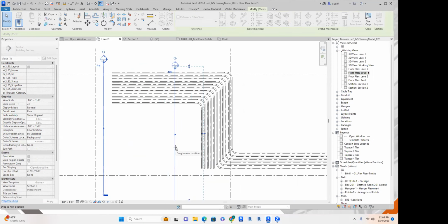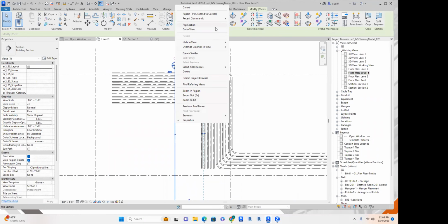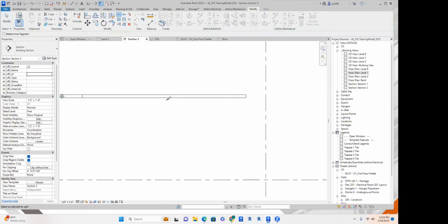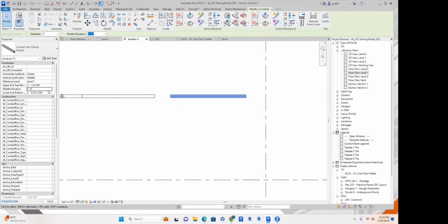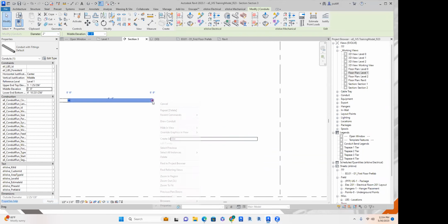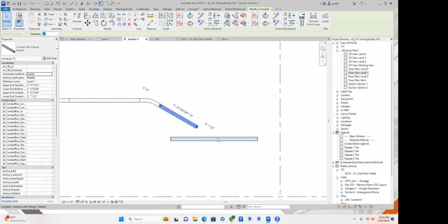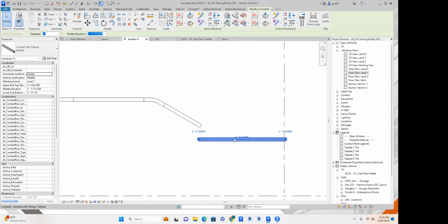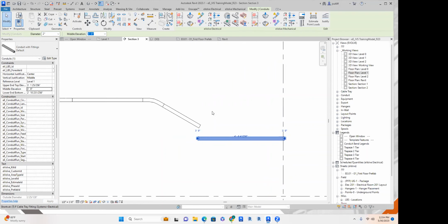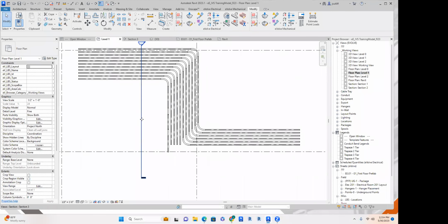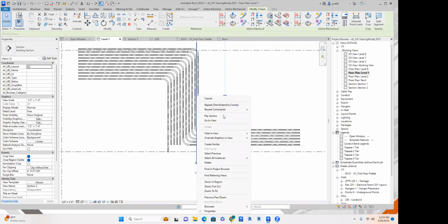And then as far as a kick and an offset, you can do that. And I've got my trusty working section here. So you can grab your conduit that you need, the offset. I'm going to just do a quick split and get the chunk in the middle, and then drop it down to my 2-foot elevation here. And then grab our conduit, draw that in at a 30-degree angle. And then I'll be able to trim these together here as well. And so, yeah, we've got our real basic offset here, and then getting into a kick as well.